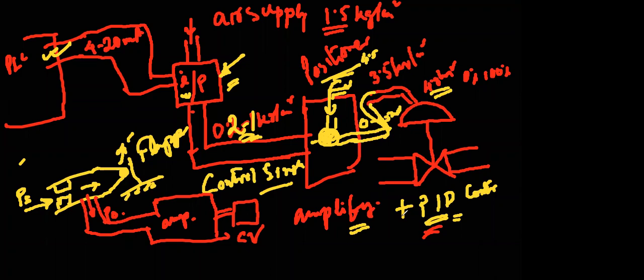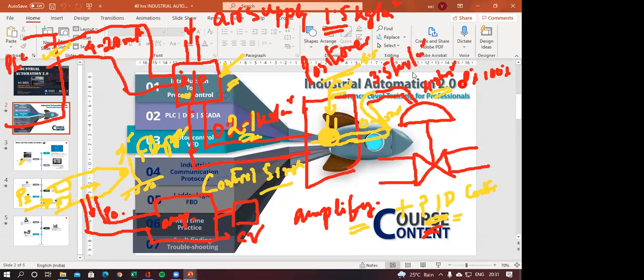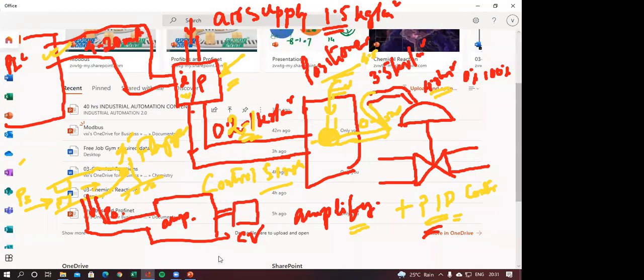So, is there any proper method or calculation, because many times our control valves start hunting. It is working from 4 to 20. If we directly apply the source and apply 4 milliampere, it comes to 0%.